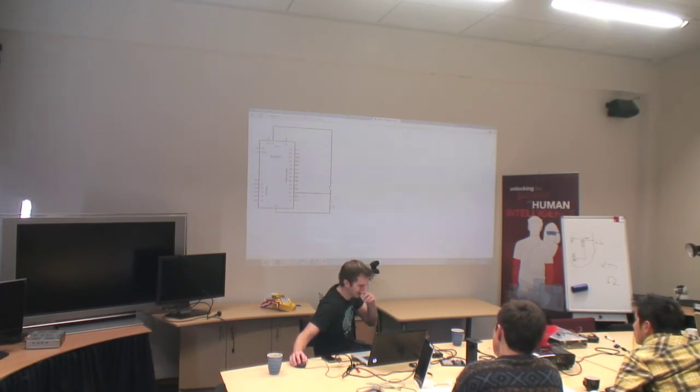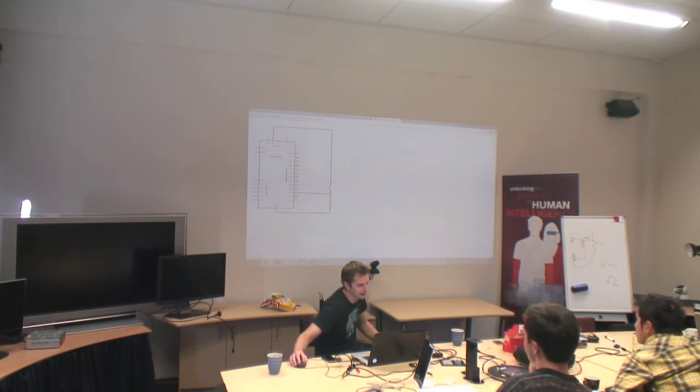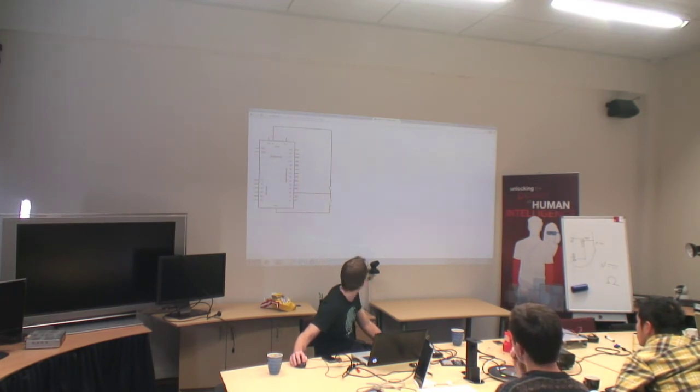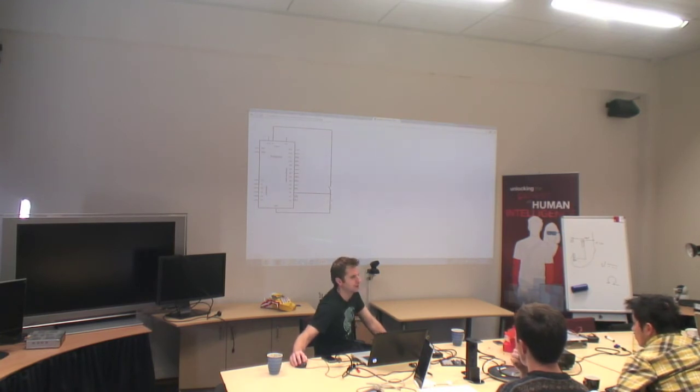If the switch is closed, then 5 volts is going to flow from here through the resistor and into ground. We're going to look at this a bit later on, but when we look at current or voltage flowing through a circuit, the voltage will be proportional to the amount of resistance. Because this is the largest source of resistance in the circuit, most of the voltage will drop across here. So on one side of this resistor will basically be 5 volts, on the other side will basically be 0 volts. So it's 5 volts here, and this will read 5 volts. Does that make sense? Yep.